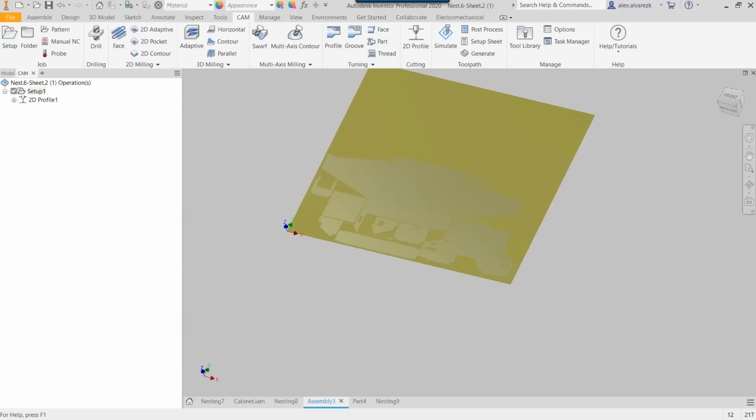I think he might be talking about the NC code, where you have the top layer or the top section that's going to be generating setup details there. And that, Jeremy, would be taken care of in the post. So if you just want comments to be outputted, like let's say we have stock size, or maybe a specific sheet that you're working with, that can all be taken care of inside of the post. Absolutely. So that's what you're referring to.